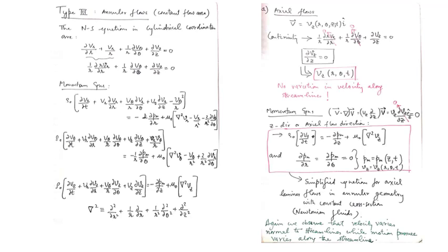And the other two momentum equations, which are radial r direction and theta direction, they again simplify in the same manner as with the flow configuration type 1 and 2, that ∂Pm/∂r and ∂Pm/∂theta are 0, because there are no radial and V theta velocities, so all the other terms go to 0. So again the conclusion is that the motion pressure does not vary along the radial and theta coordinates, so it can be varying only along z and of course with time. So Pm is a function of z and t, and Vz is already shown to be a function of r, theta and t, right.